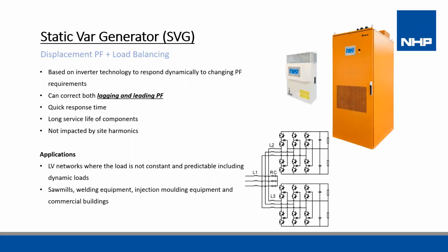Now let's look at a more advanced technology, static Var generators, or SVGs. As the name states, it generates reactive compensation based on inverter technology. It can respond dynamically, that's the key word there, to power factor requirements. SVGs can correct for both lagging and leading power factor. They have a very quick response time,